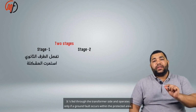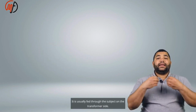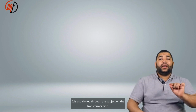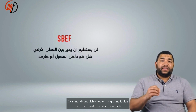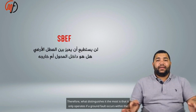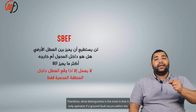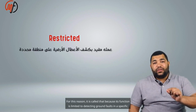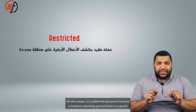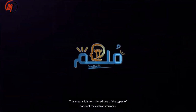Restricted earth fault protection is fed through the CT on the transformer side and operates only if a ground fault occurs within the protected area. It cannot distinguish whether the ground fault is inside the transformer itself or outside. Therefore, what distinguishes it the most is that it only operates if a ground fault occurs within the protected area. For this reason, it is called that because its function is limited to detecting ground faults in a specific area only. This means it is considered one of the types of unit protection for transformers.